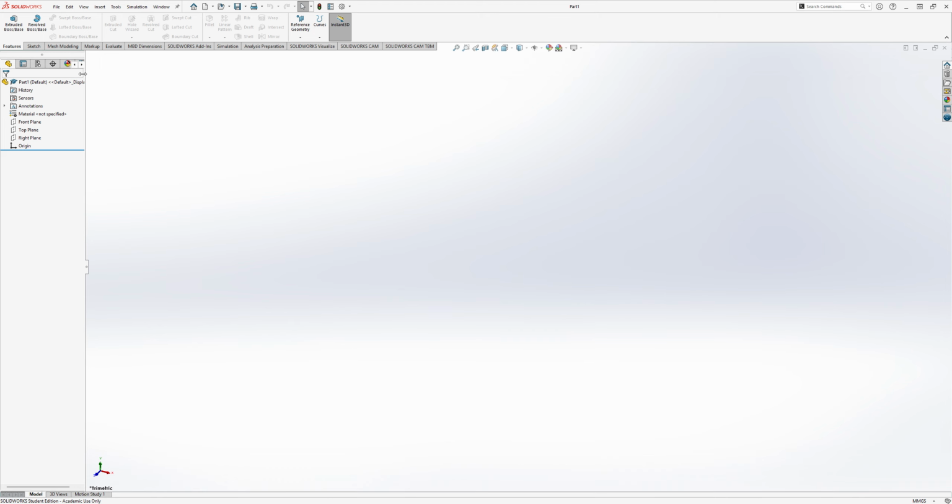So first thing we need to do is to create a sketch of whatever we want to make. In SolidWorks or any CAD, a 2D sketch is then created into a 3D model. To demonstrate that, using your mouse pointer, go to this toolbar where there's a bunch of words such as features, sketch, mesh, modeling. You may not have as much as I do, or you have more. Ignore that for now. So across from features there is sketch, so we're going to click on sketch and we're going to press this sketch button.